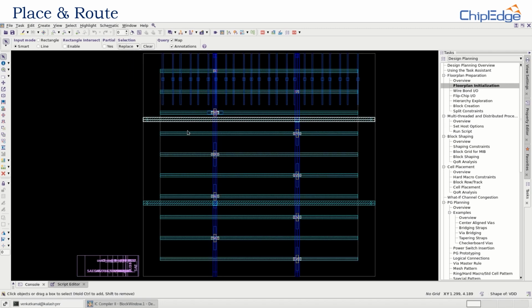And all the metal layers are evenly distributed between the stages, and some are used in floor planning, some are used in power planning, some others are used in placement, and some leftover are used in CTS and routing. Some metal layers like M6 and M8 are used in CTS, or M9 and M7 are used in routing, or some others are used in placement or power plan stages.